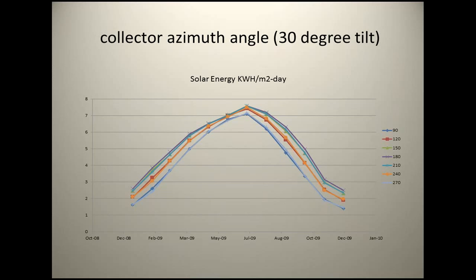But it doesn't make much difference in the summertime. The amount, by percentage of total solar gain you get, even if you're east and west facing, really isn't very much. And it's better if you're flatter because then you're just seeing the sun overhead. So it's a big deal if you're really trying to gain energy in the winter months. But you're going to use a hybrid system anyway, so there just isn't that much penalty for being off.